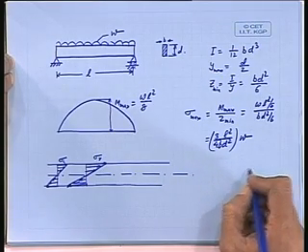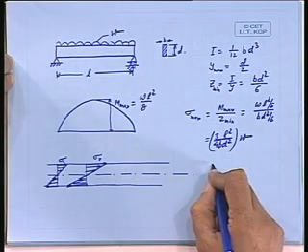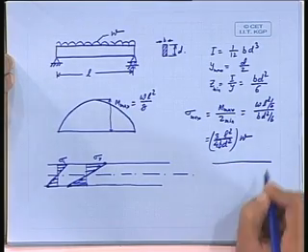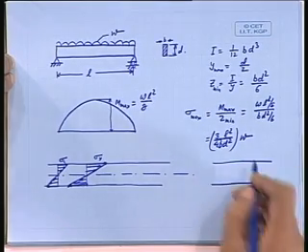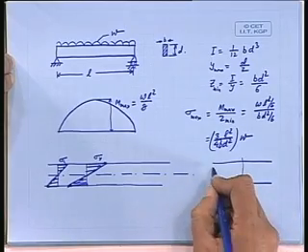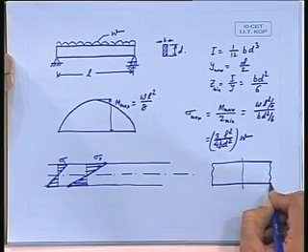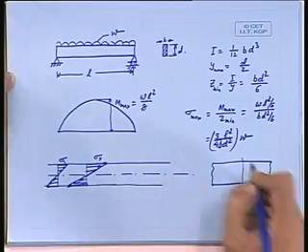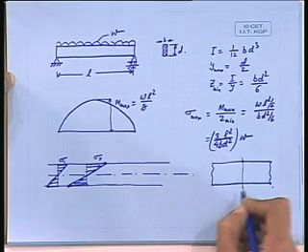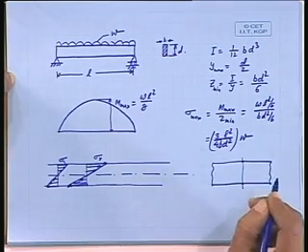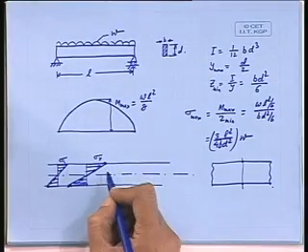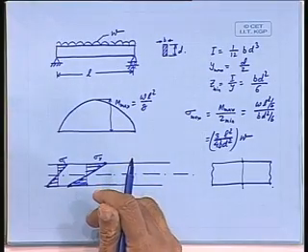Okay. In this case, what happens to this part of the beam? Let me draw the beam here also. This is the section under consideration. So at this stage, the stress reaches at the extreme fibers to a value sigma Y. And below that, all over, the stress is less than sigma Y and the entire section is still within the elastic limit.